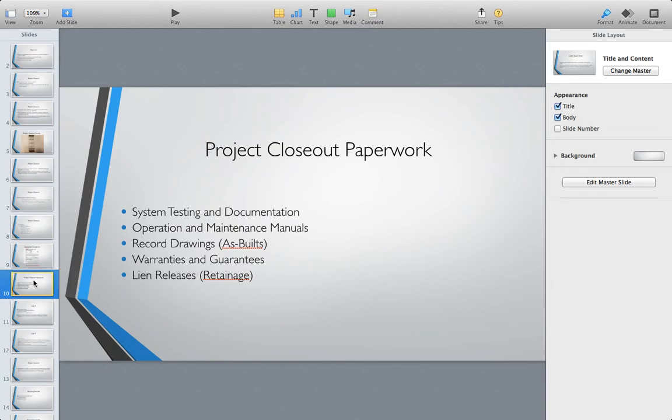So sometimes the CM might even have the commissioning agent come in and give them a tutorial. Sometimes the vendor will be present and let them know how to reach optimal operation, so the system doesn't break down, and they have the knowledge to maintain it.